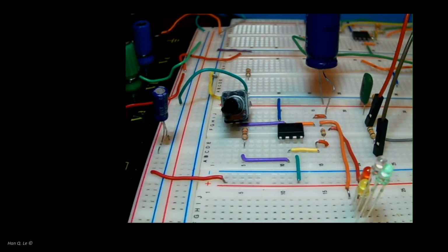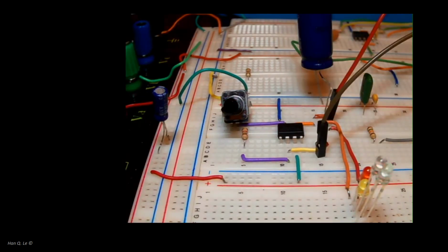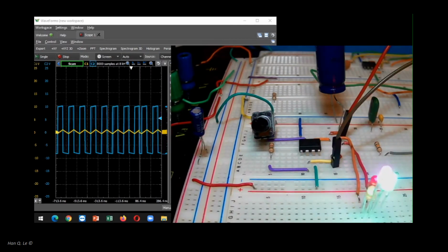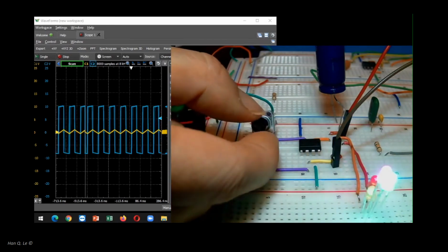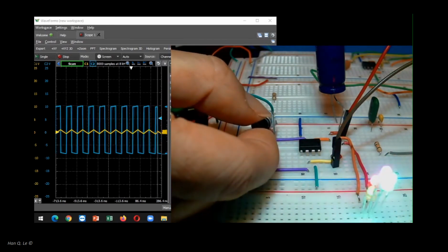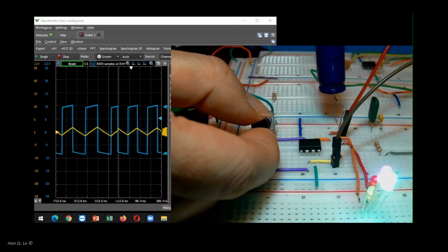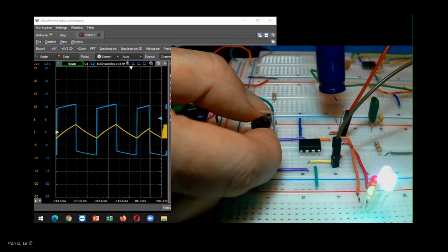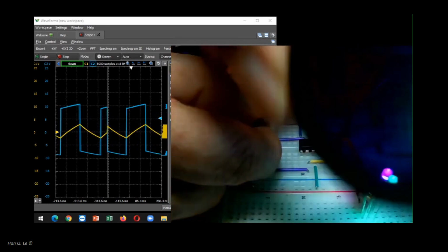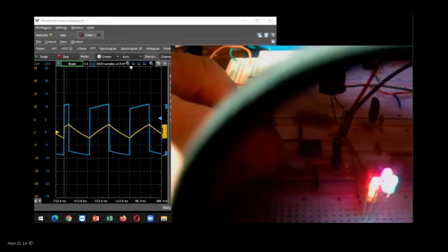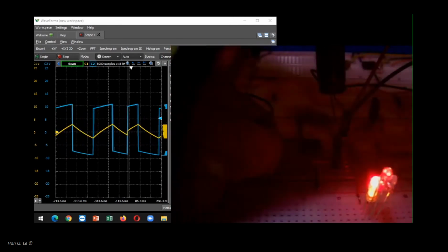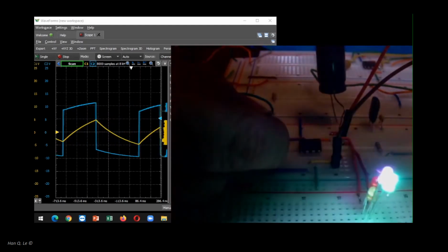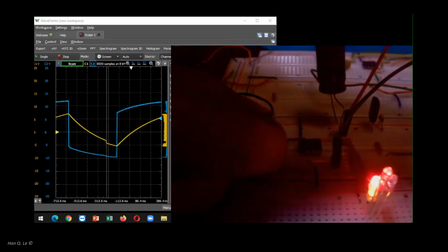Once the circuit appeared to work as expected, measurement or monitor should be set up for data collection. The LED's emissions are more complex than what the camera and the scope trace can show. The yellow scope trace only shows the voltage across the capacitor. The LEDs actually have a short drop-off after the initial flash, and the two types, the reddish and the bluish, have different behaviors as well. This can only be measured with a photoreceiver as shown in another video.